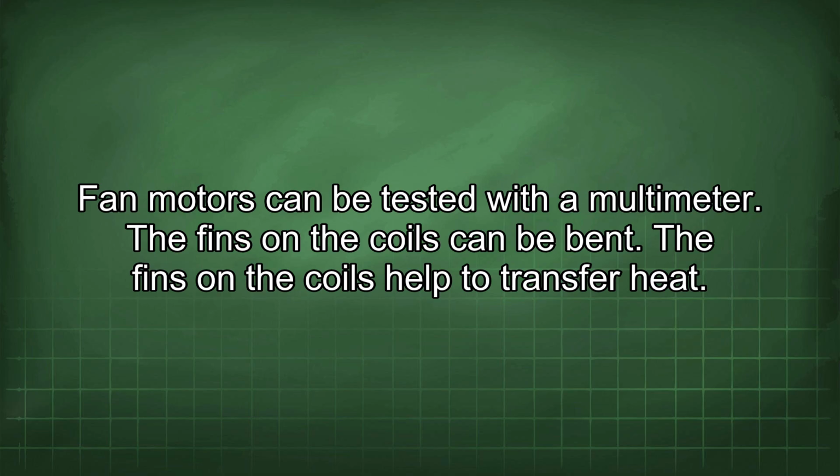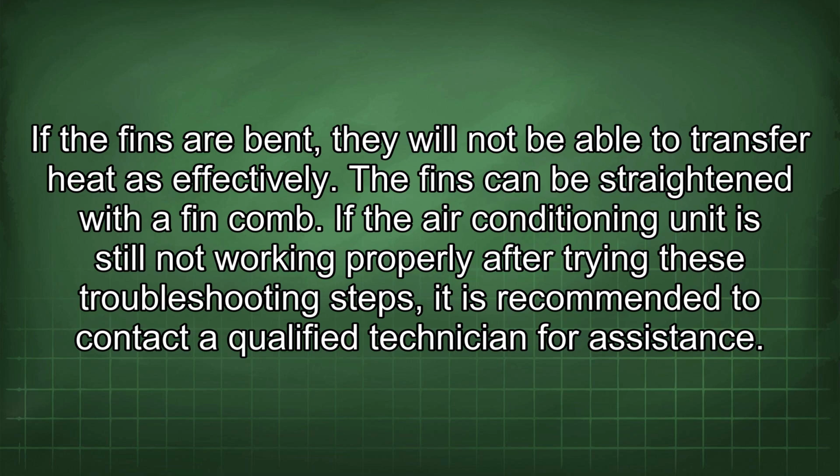The fins on the coils can be bent. The fins on the coils help to transfer heat. If the fins are bent, they will not be able to transfer heat as effectively. The fins can be straightened with a fin comb.